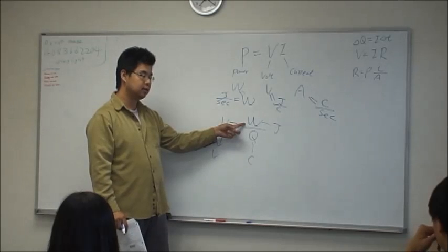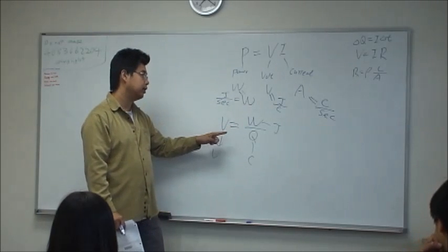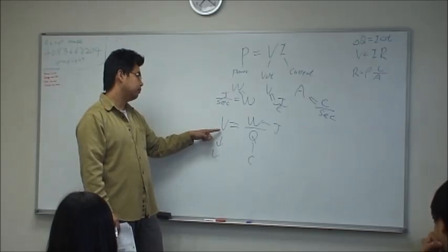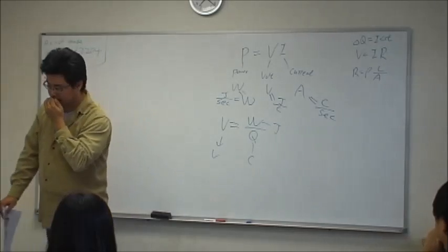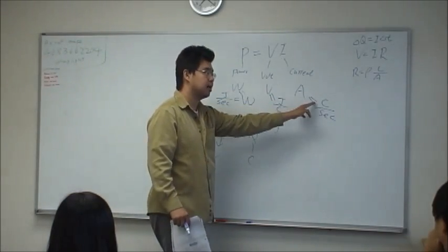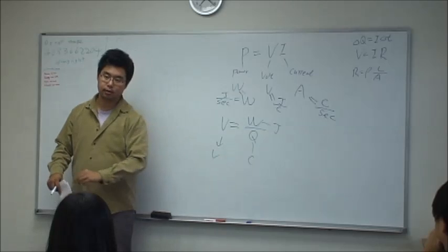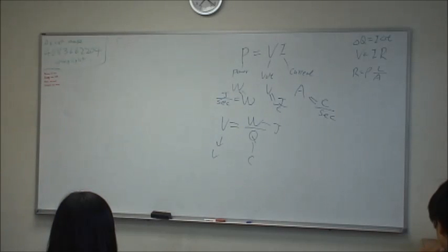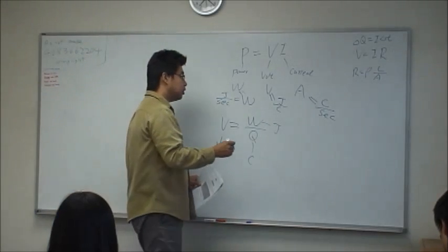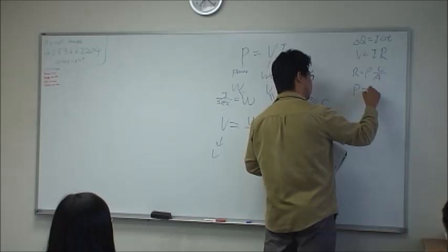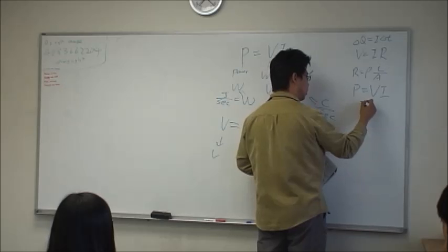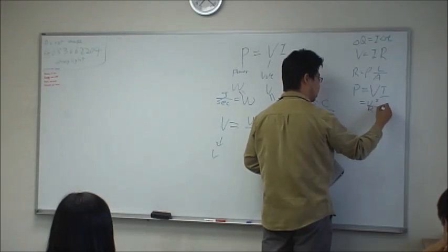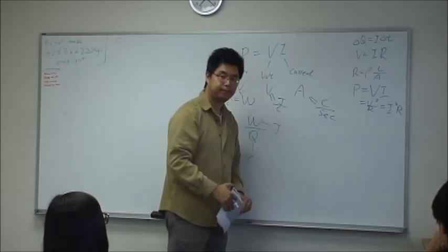So this is from the very beginning when we started to define the electrical potential. We want to talk about the energy to move a certain charge. That's why we define the potential. And suddenly we found that by multiplying this voltage potential with a certain current, we again get the power. Because this current is how many charges we are moving, just like the charge here. So I will finish the loop, self-consistent. Instead of the power equal to voltage times the current, if we put V times I into it, it will also equal V square over R and I square times R. Make sense?